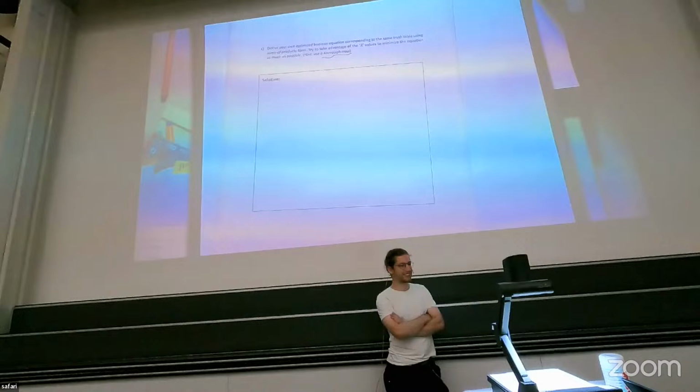Now, how many entries do I have here? I have 8 address bits, so it's 2 to the 8, that equals 256 words. Each one of them is 32 bits, or 4 bytes. Agreed on this? So that's a 1 kilobyte memory.